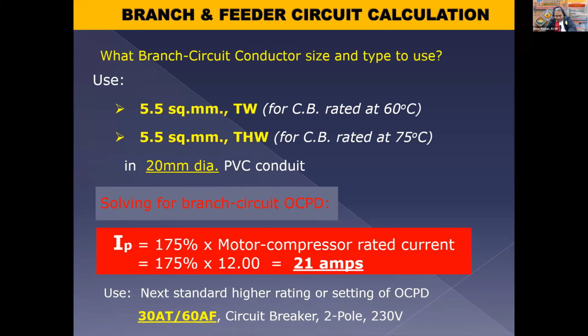So if we're going to use the next size lower, the problem is we might not be able to coordinate the motor during starting, no? So it could trip. It could cause noise and tripping. So that's a problem now. So we're going to use the next size higher.